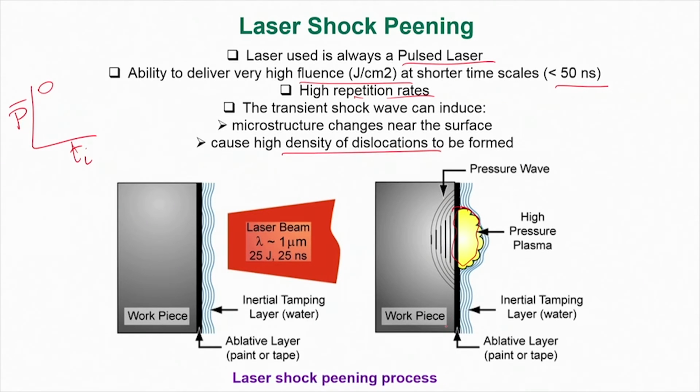The beauty of laser-assisted shock peening, please remember we are talking about shock peening and not shot peening, is that it affects a very thin layer, typically a few tens of micrometers or even less. There is no dimensional change, no compositional change, no distortion, yet the surface develops fairly high, a few hundred megapascals of residual compressive stress.